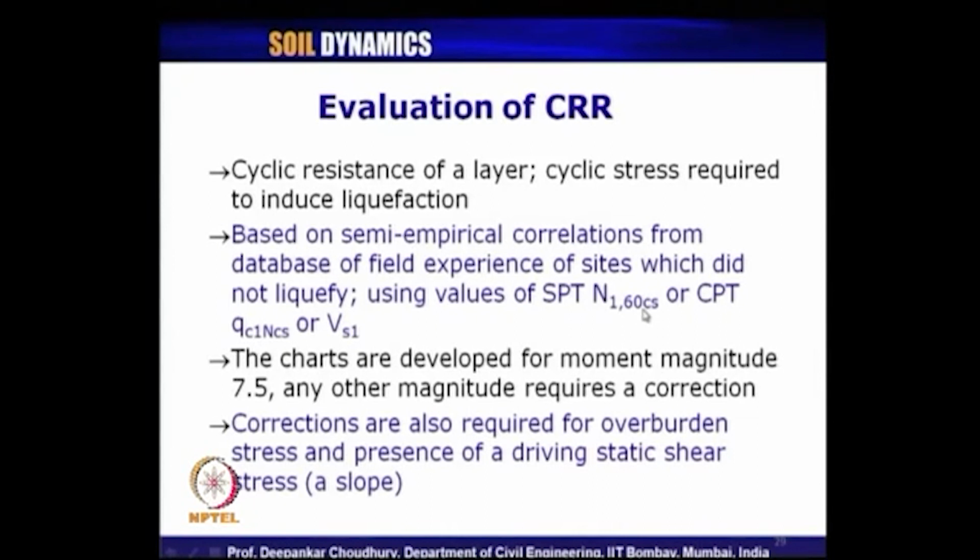I will explain them soon in the forthcoming slides. What do they denote? The charts are developed for moment magnitude of 7.5. I have already mentioned CRR is computed or referenced. The reference is taken at moment magnitude of 7.5. So, that means any other magnitude requires a correction.